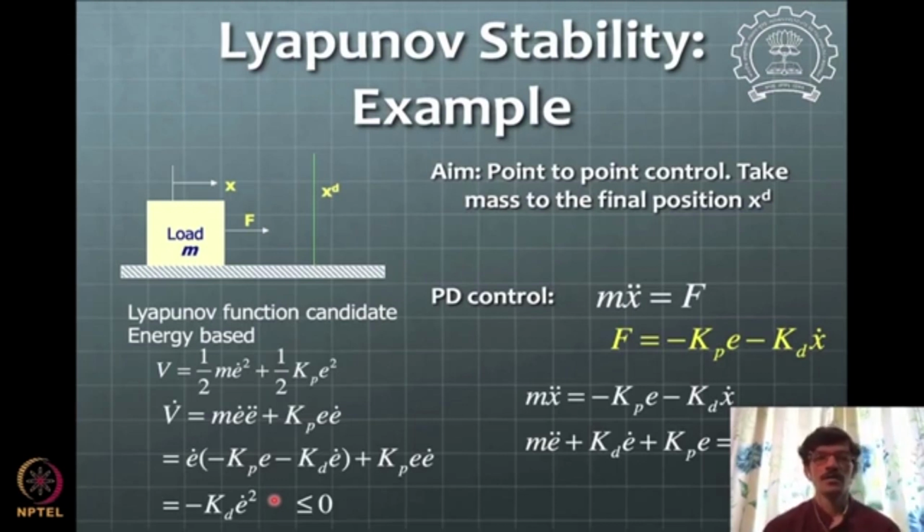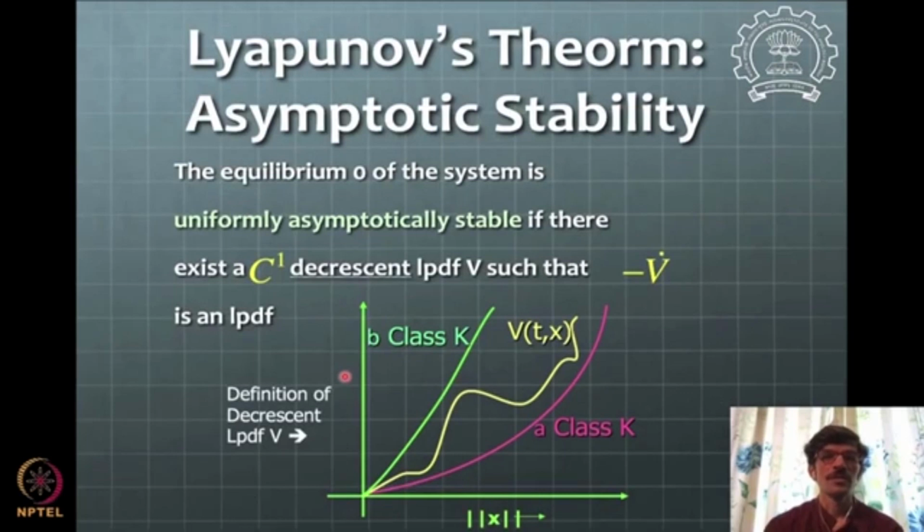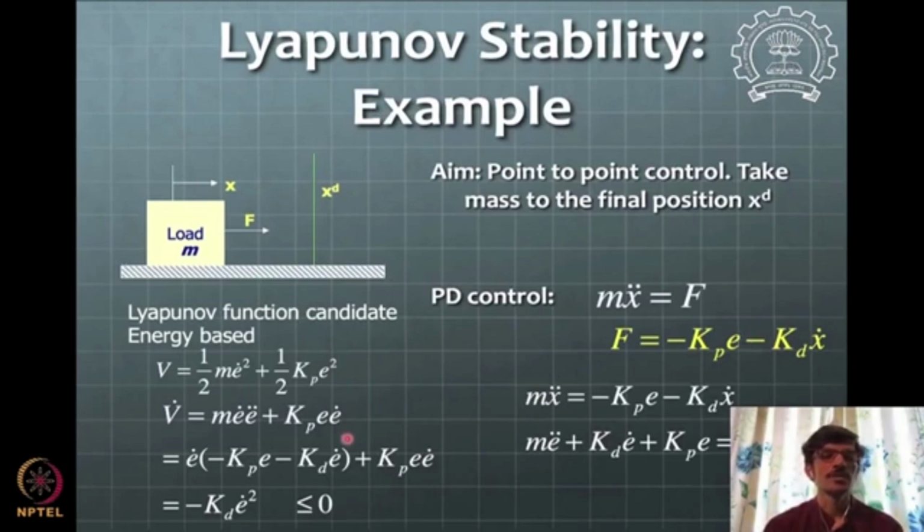And remember again, these rules of the Lyapunov theorem are only the sufficient conditions. So if these conditions are satisfied, then you say the system is stable. If they are not satisfied, that doesn't mean anything. You cannot conclude anything about that. If these conditions are satisfied, then you have this result available. This is a very important thing to know: because you are not able to find any V which will satisfy these conditions, you cannot conclude that the system is not stable, or conclude the otherwise result. These are only sufficient conditions.